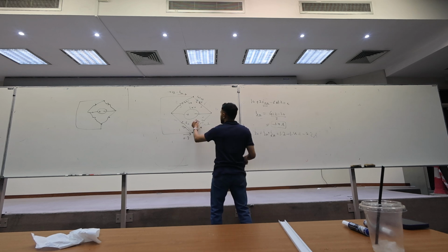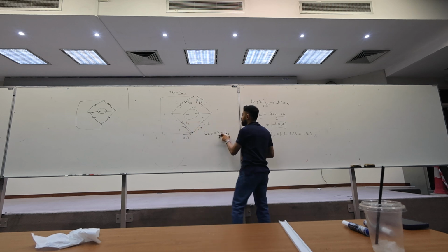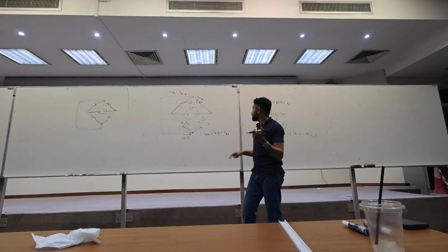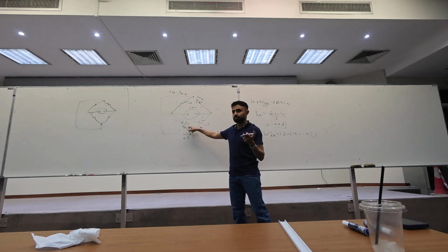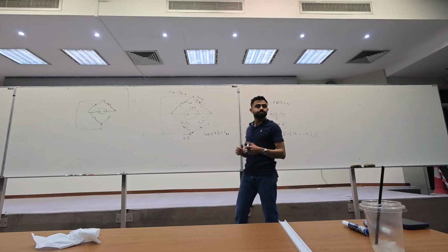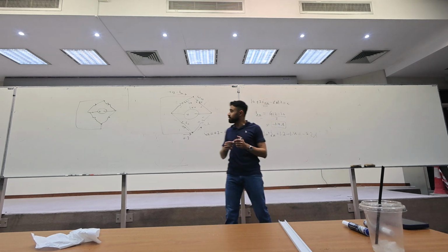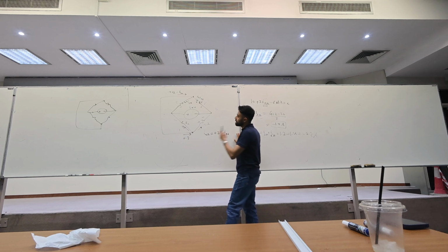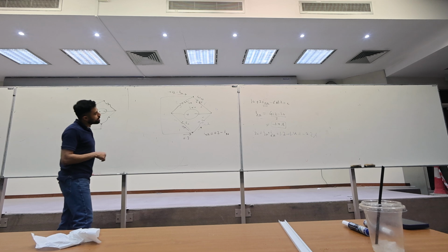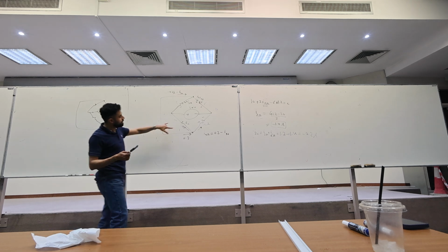So you will have a KVL here with only one variable, which is IRx. But there is another problem. IRx, we don't know Rx. Can't I do a KVL from outside? You can do an outer KVL. We can do KVL here, but this is a 0 from the 4 ohm.